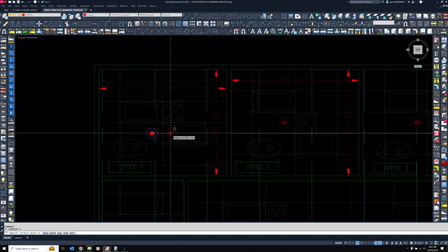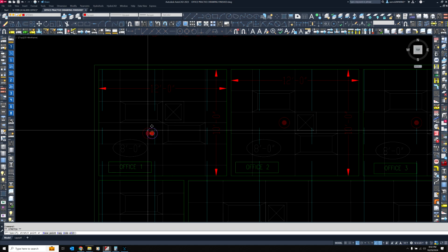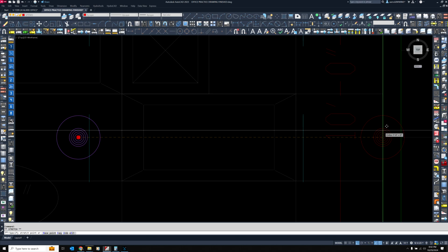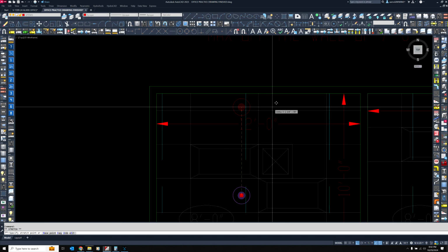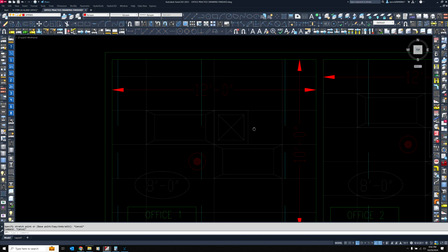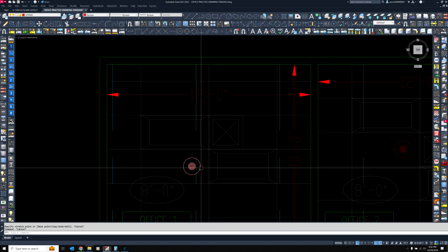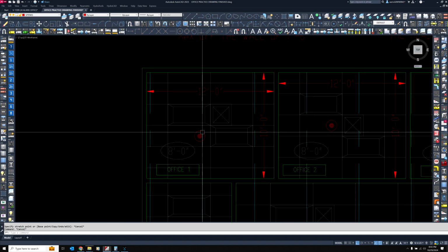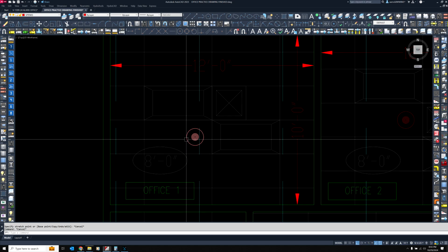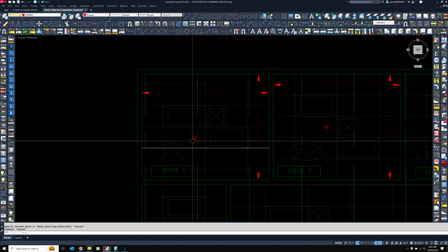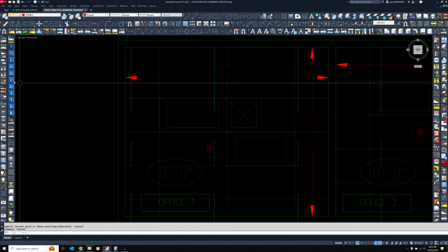But instead of this being a 10 by 12 room and this sprinkler head protecting 120 square feet, we know that we are 7 foot off that wall and 6 foot off that wall, which means we are actually 14 foot by 12 feet. It makes a big difference in the way we do our hydraulics. The amount of water you need will change when the area your head is protecting changes. So make sure you're following me.